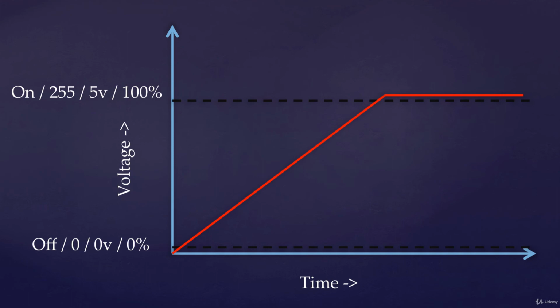So when you read a sensor or when you're outputting, the number that you put to this input or output is between 0 and 255. The reason for that is because everything is in base 2, so it's 2 to the power of something. And when you put 2 to the power of 8, it becomes 256, so it uses an 8-bit analog to digital converter. Just a little bit of extra knowledge, whether or not you needed that.